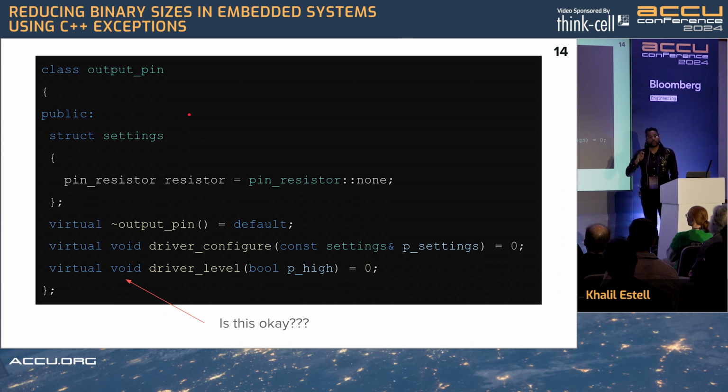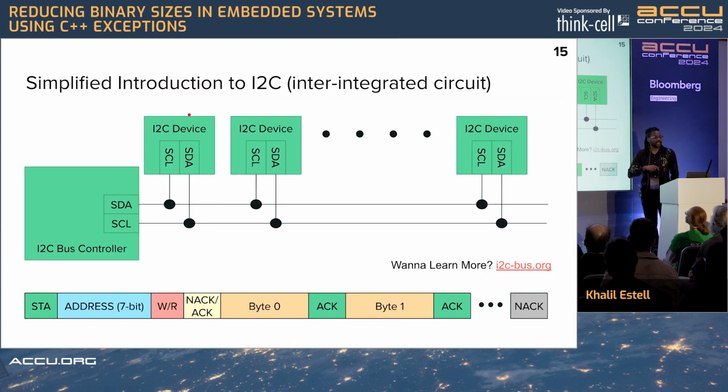We're going to make a slight detour over to I²C. So I'm going to go over a very simplified talk about I²C. It is a hardware communication protocol. It is how we can talk to multiple devices, usually sensors, with only 2 wires. There are 2 signals here. We have SCL, serial clock, and SDA, our serial data line. The serial clock is used to qualify signals on the data line and basically sync up with those signals and acquire them into the device.